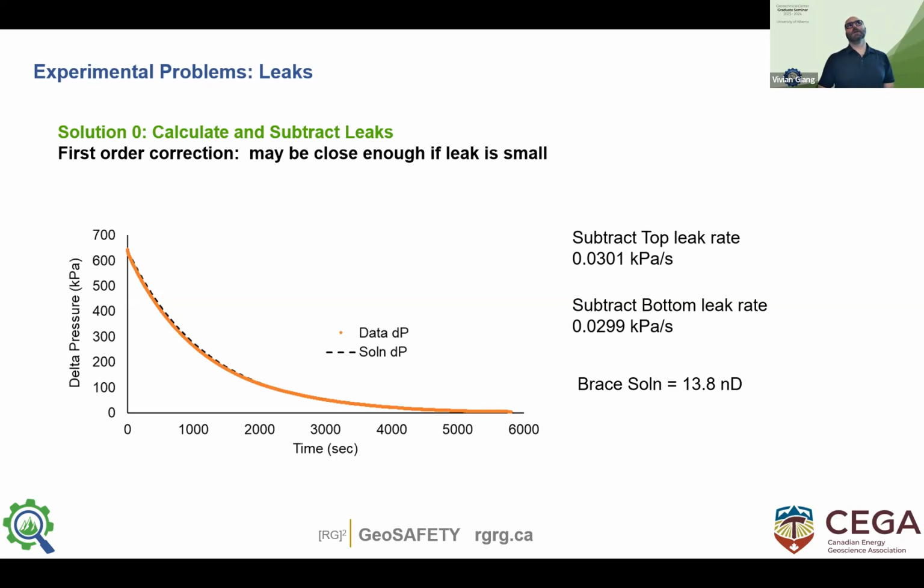And then we put the pore pressure all the way up to 10 MPa and let it sit for another 3, 4, 5 days. Then we say we think we're saturated, and we run a test, which takes 20 minutes. So lots and lots of work to get to a state where we think we've satisfied all the assumptions of the test.